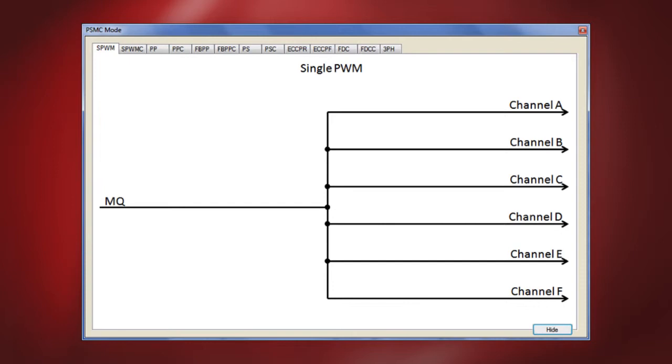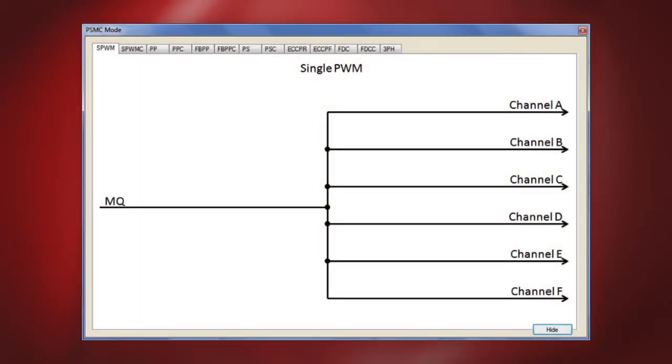Let's look at a few of the important modes of the PWM and the intended applications which can benefit from these modes. There are 5 fundamental modes of operation, 1 high-resolution frequency mode, and 1 6-step mode that simplifies steering pairs of outputs to the 6 PWM channels. All modes except the 6-step mode have a corresponding complementary output mode, making a total of 13 modes achievable for the PSMC module. The complementary modes include 2 deadband controls, 1 triggered by the rising edge of the PWM signal and 1 triggered by the falling edge.